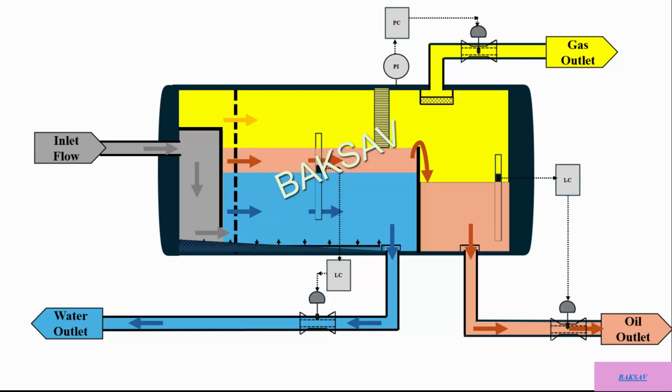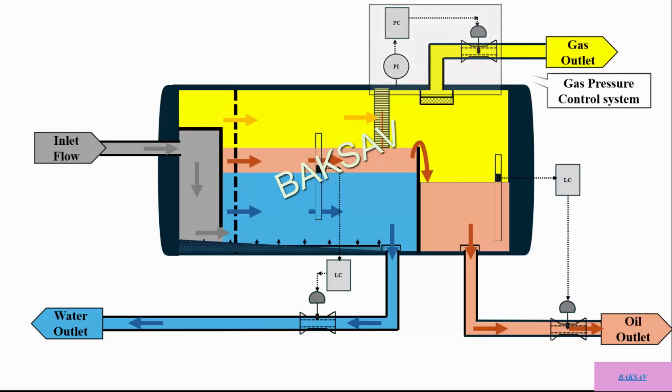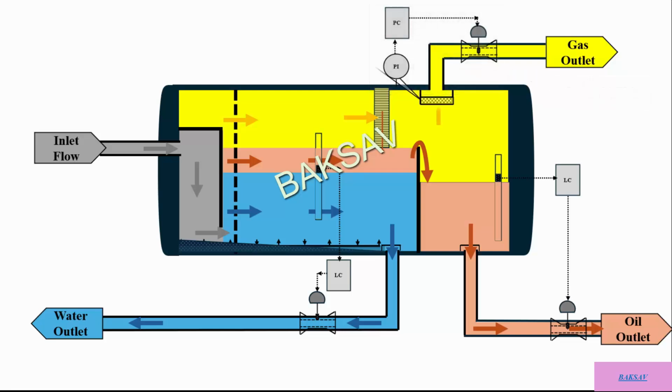Separated gas passes through defoaming plates, which break up the foam and allow the foam to collapse into the liquid layer. As the separation process continues, additional gas volume enters the vessel and the separated gas pressure rises. Excess gas leaves the separator under control of the separator's pressure control system as described previously. Before leaving the separator, separated gas passes through a mist extractor or mist eliminator, which captures small liquid droplets from the gas. Those droplets are also collapsed into the liquid layer.